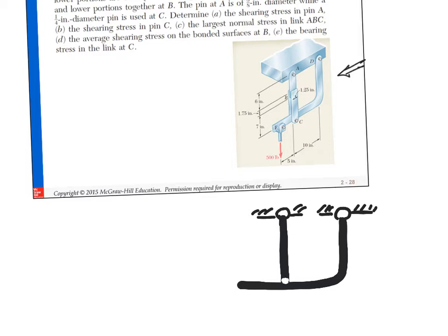So I will open this up and make it round. Now, why did I make it round? Because this is a hinge. Again, how did I know it's a hinge? It's one bolt. If one bolt is attached over here, that means it is free to rotate. Free to rotate means pin connection. Pin connection means what? It means it only has the components X and Y. No moment. We agree on this?